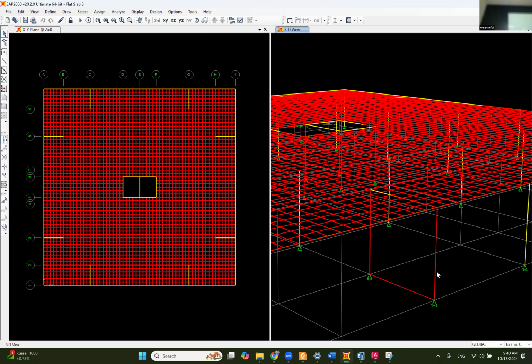Okay, thanks. So yeah, here, that's the wall, this way. And the slab is connected to this wall here, but let's say this is the whole mesh of the wall, and there's a mesh area from the slab coming loading on this wall like this. This wall is not going to feel anything from the slab, only at this joint and this joint. Any loads that come from the joints in between, it is not going to feel. And this is not how it's going to deform. The deformation is going to be separated from the wall. You will feel that the slab is actually not connected to the wall, only here and only here.